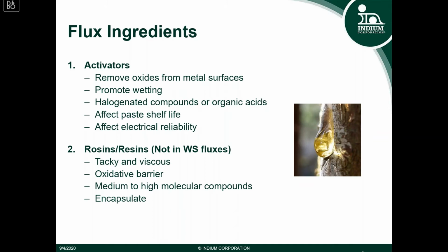Rosin is exactly tree sap. Then you have resins, which is synthetic rosin. Rosins and resins are not used in water-soluble fluxes, which is why we're only talking about no-clean and RMA fluxes today. Rosins are tacky and viscous, and as I mentioned, they encapsulate any harmful chemicals that can pose a threat to electrical reliability. They make the flux residue benign. They act as an oxidative barrier during the reflow step, and typically they're medium to high molecular weight compounds.